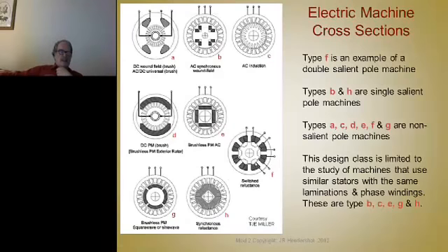So in reluctance machines, the torque and performance you get is based upon how well you can create this saliency, or how big a difference you can design into the geometry such that one inductance is a lot higher than the other. So the inductance ratio is equivalent to the saliency ratio in these kinds of machines. That's what I wanted to point out.